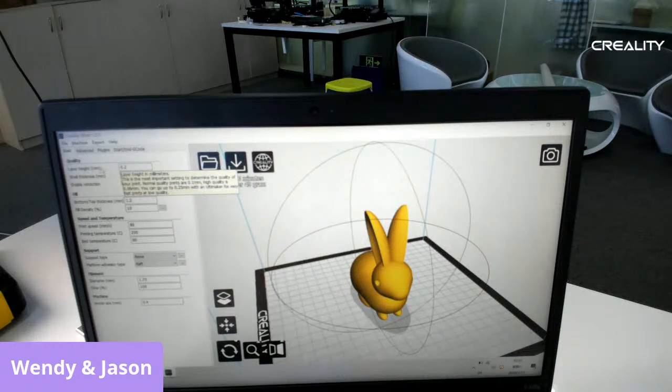If you want a decent print with detail, you probably want to keep this layer height small. The recommended setting is hard to say. Myself, I would say anywhere from 0.15 to 0.2 would be okay. I have tried 0.4, and it's not that good.